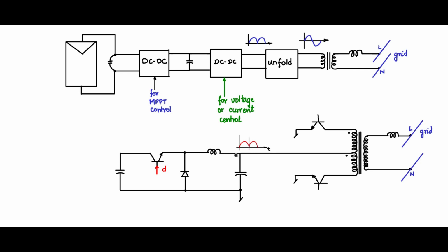You see this V0 for a buck converter, V0 is equal to D times Vin. Now if D is made sinusoidal in nature, that is only rectified sinusoidal in nature, you will get an output V0 which is Vin sine of omega t, and therefore you will be able to get this kind of a wave shape. Now this wave shape is given to the center of the push-pull. Let us say these half sinusoids have 10 millisecond width. So two half rectified sine waves will make 20 milliseconds, which is 50 hertz.